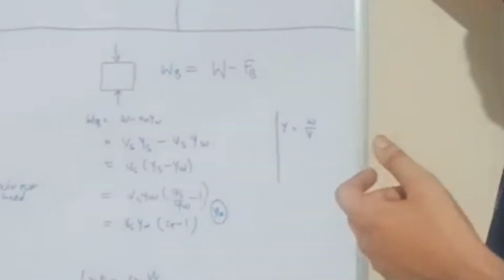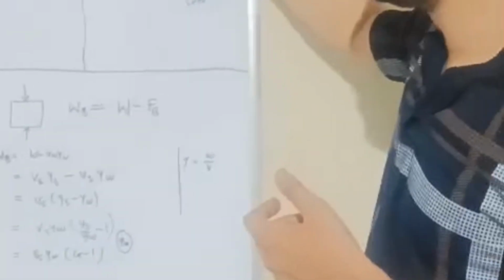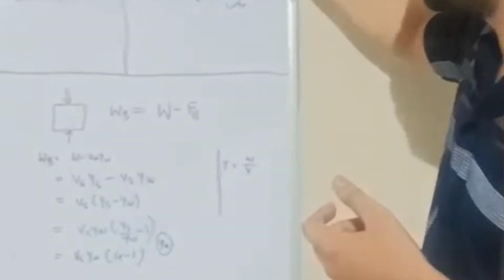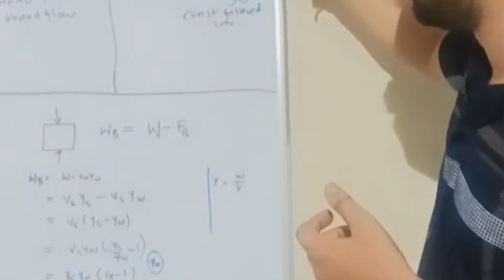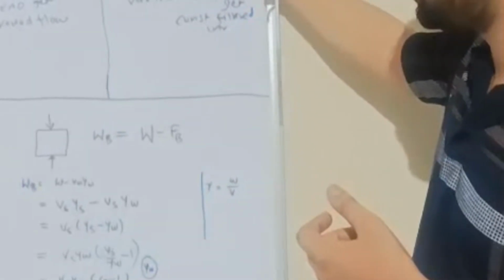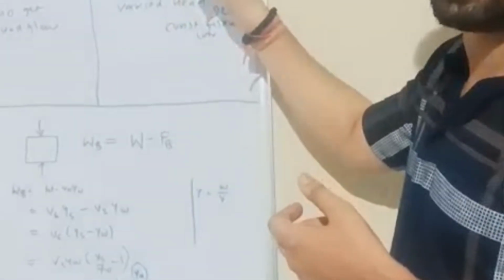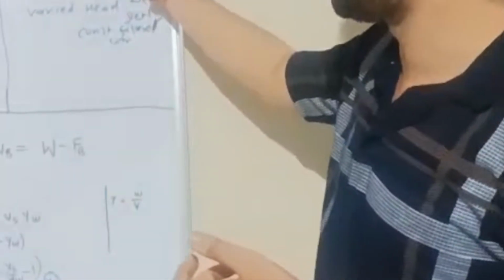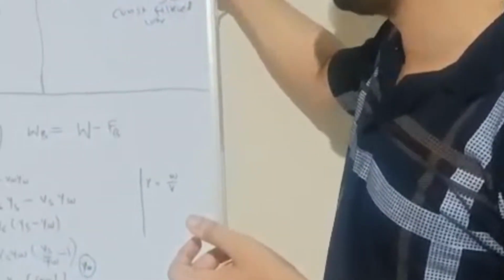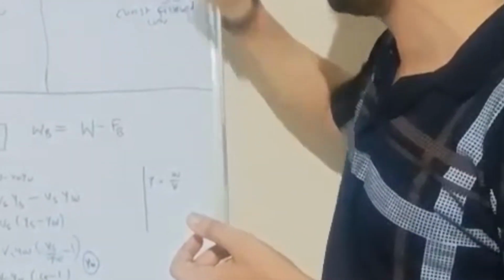But in varied head, when the static head of water becomes equal to the resistance offered by the sand layer, vacuums are created, and at that time we have to provide extra water over this pre-selected head.